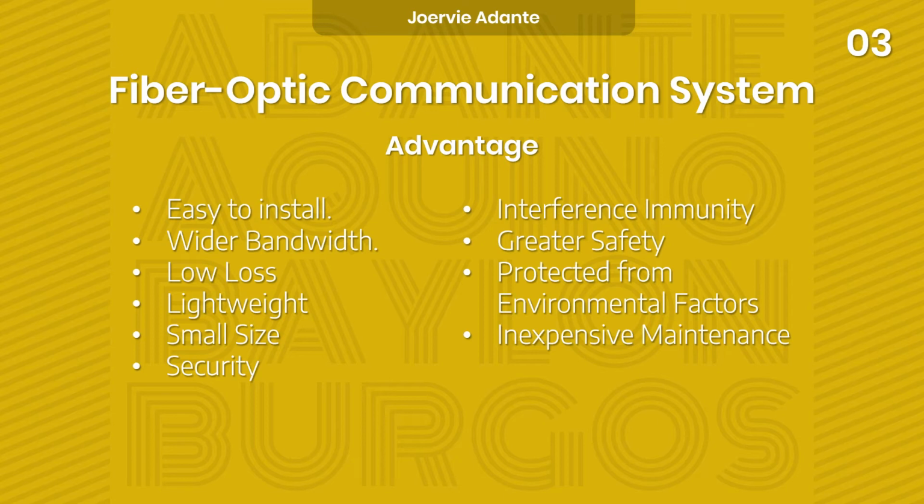Fiber optic cables do not radiate signals, as said earlier, as some cables do and cause interference to other cables. They are immune to the picking up of interference from other sources. They are immune to crosstalk between cables caused by magnetic induction and also immune to static interference caused by electrical noise sources. Greater safety.